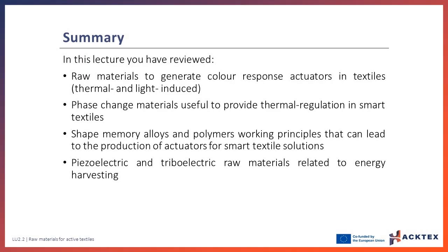In this lesson you have reviewed the raw materials to generate color response actuators in textiles, focusing on those thermal and light-induced. The phase change materials useful to provide thermal regulation in smart textiles. The shape memory alloys and polymers working principles, that can lead to the production of actuators for smart textile solutions. And the raw materials related to energy harvesting. More specifically, the polymeric piezoelectrics for generation of sensors, and the triboelectric principles to create generators.